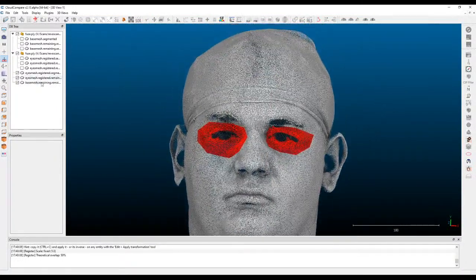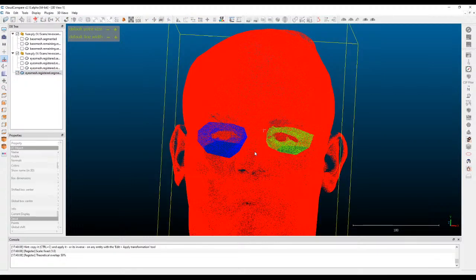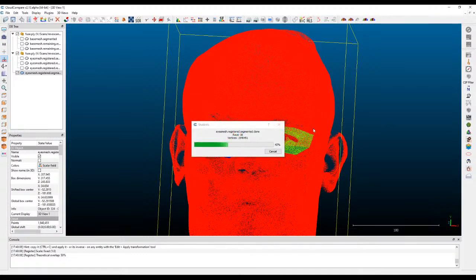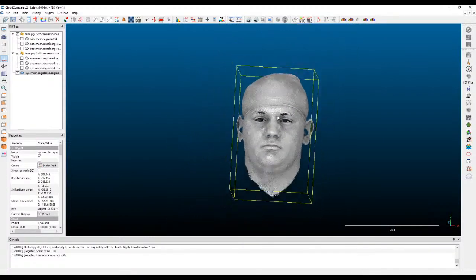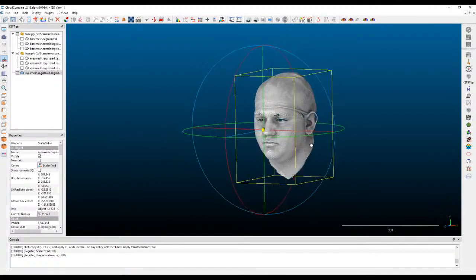So with this selected, we'll just select all the point clouds that we want to merge, and we'll merge the multiple clouds into one. Let's do another ambient occlusion just to check our scan, and if we zoom out we can see the result.